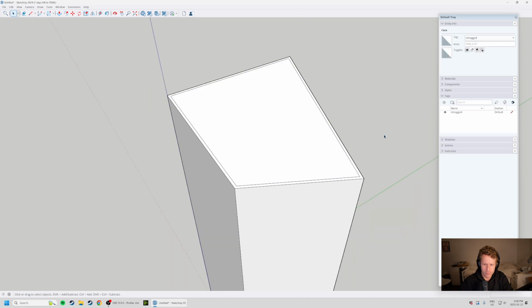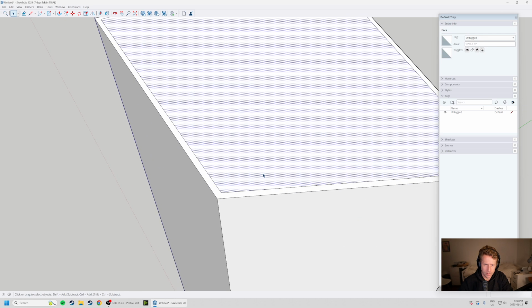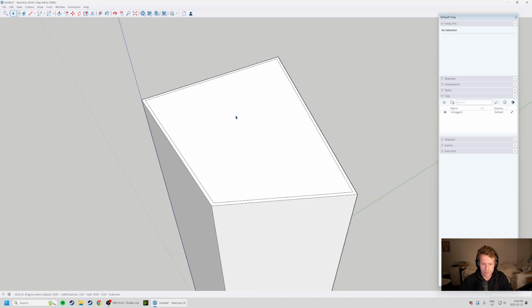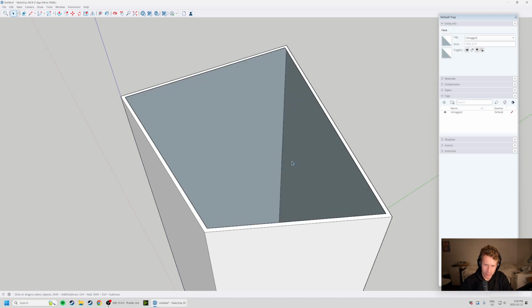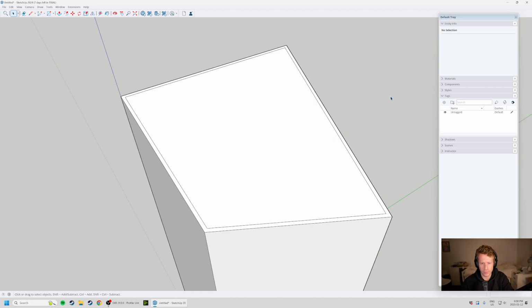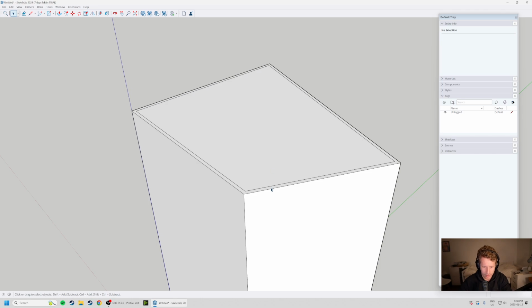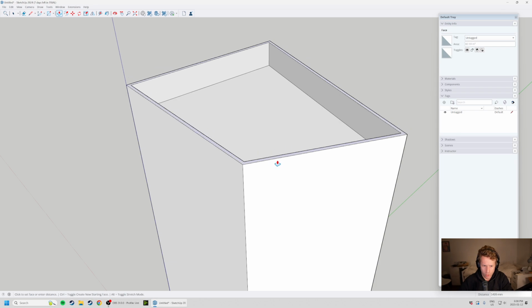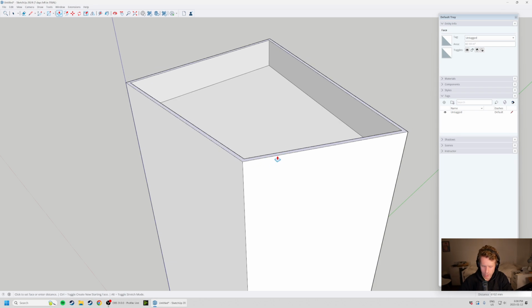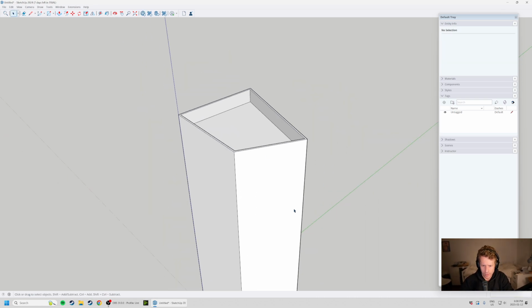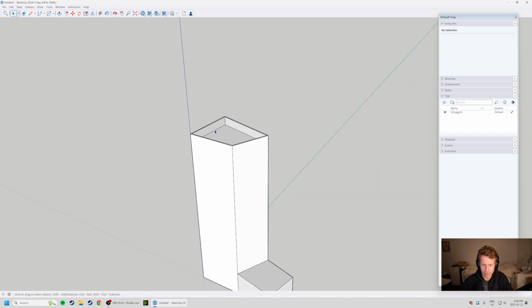And now we've got, again, 2 faces, right? So again, back to face-based modeling. If I click this face and delete it, my building is hollow. This is not solid-based modeling, it's face-based modeling. So everything needs to have a face to it. If I jump up here, I can hit P for the push-pull. I can click here and drag this up a little bit. Let's call it 6 meters, a little big penthouse enclosure here, something like this.